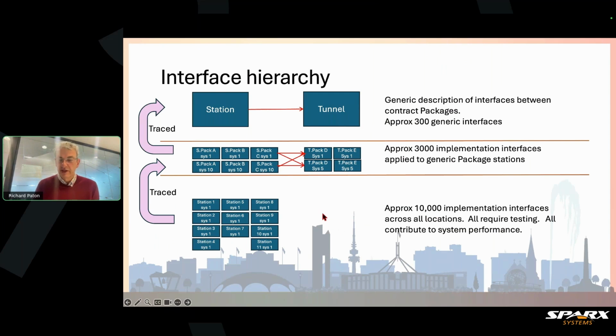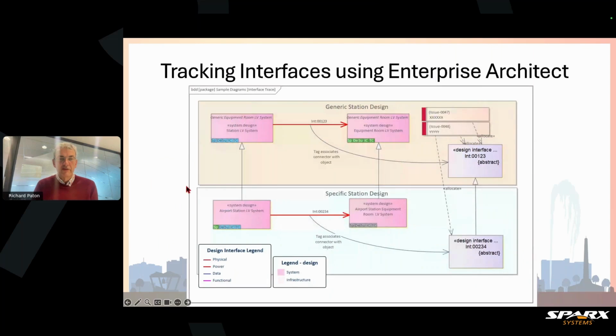And we have to track all of those, and we don't want to track them individually, so we need to be able to trace them up from here to more generic to understand their attributes. Unfortunately, tracing between one line and another line is a bit ugly. When you link two lines, there is an object called a proxy connector which is created on each line, but each link creates a new pair, and it's very hard to visualize and to track those.